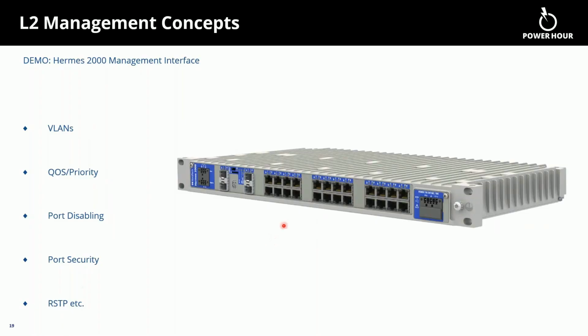So I won't go too much into which one's better, why you would use them. There's also IEC 61850 specific ones called PRP and HSR that are quite good. So that's a decision you have to make of what you're going to use. We do have one question. If you configure VLANs, is the question, are the ports completely isolated? And I'm going to click on it, make sure I got the whole thing. And he's saying, well, how well does this keep a network separate?